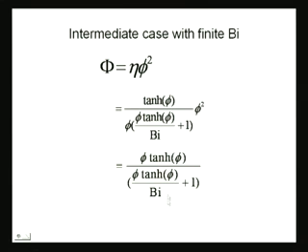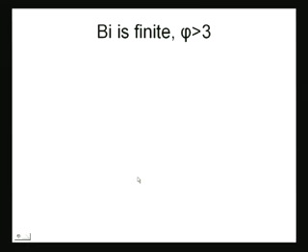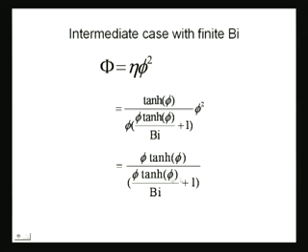Eta that you have over here goes as phi squared, I think. If this is very small, then this remains. So I think Biot number over phi squared. Okay, right. So Biot number goes to the numerator. So you will have phi tanh phi plus Biot number, and 1 goes to the numerator, so this one you can neglect.